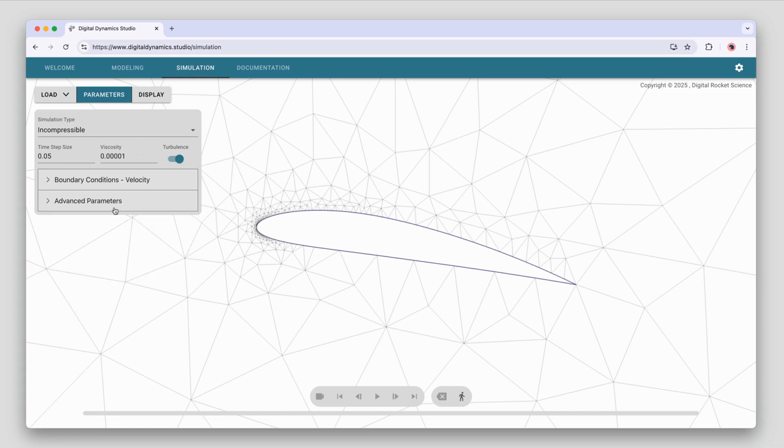In this case, since the boundary layer will not be modeled as accurately as it was before, we can go back and reduce the mesh size limit back to 1. The mesh isn't going to be nearly as large in these simulations since it won't be throwing so many nodes and elements in the boundary layer along the airfoil. In this case, the mesh will be much smaller and the simulation will be carried out much quicker.